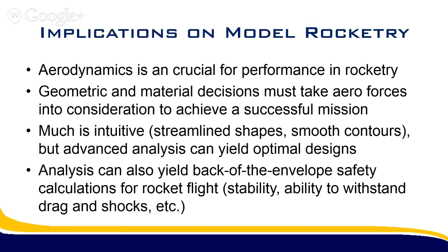Or you could say if you're going to be going near the speed of sound, your center of pressure is actually going to change because of that Prandtl-Glauert rule. It doesn't apply to just drag; it actually applies to all aerodynamic forces like lift, pitching moment, and that normal force as well. So you can say that normal force coefficient is going to change with Mach number as well.